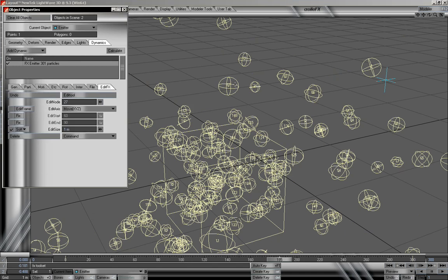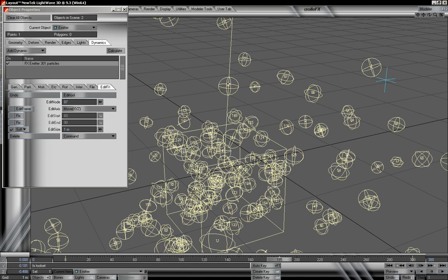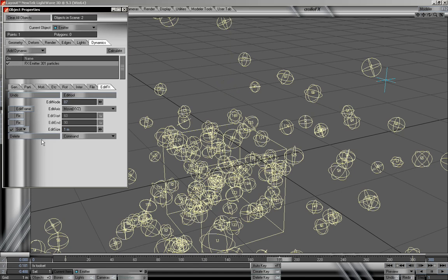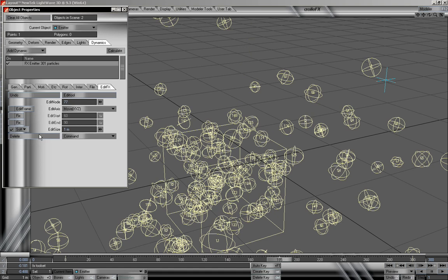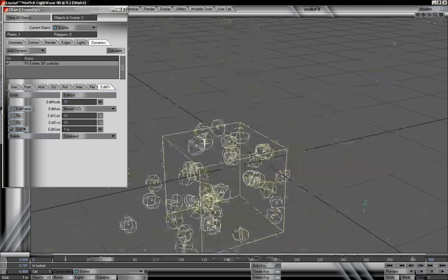And what we could also do, if I go to our edit tool, I'm going to select one of these particles and I can hit delete. And that will just remove a particle from that emitter completely. So if you do have a stray particle kind of shooting off in your scene, all you need to do is select your particle, hit delete, and then you can remove it entirely from your object and just kind of get rid of those different ones that will show up.